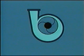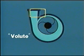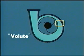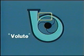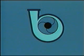As it does, what happens? It enters a specially designed area of the casing known as the volute. The volute is wider at the discharge nozzle than where the fluid leaves the impeller. There's more space, which causes the fluid to slow down. Its velocity decreases. The fluid gives up some of its energy.